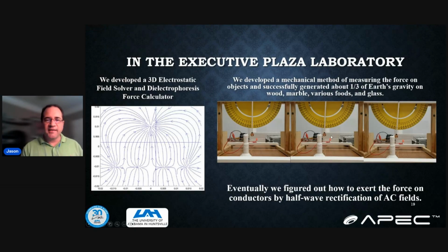Now, one of the fun things about doing this is learning how to suppress arcing. And the really good commercial insulators are very expensive, like high voltage putty. I'm sure some of you are familiar with high voltage putty. One of our undergraduate students at the time we did these experiments kind of sheepishly approached me and said, you know, I used to use as a kid this stuff that was called Sculpey. It's an art clay. And she goes, do you think that might work? And I said, well, hey, it's worth a shot. I mean, we can set it up and try it. Why not? So she brought some in and it worked beautifully.